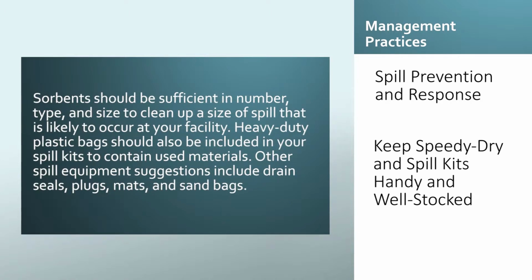Sorbent should be sufficient in number, type, and size to clean up a size of spill that is likely to occur at your facility. Heavy-duty plastic bags should also be included in your spill kit to contain used materials. Other spill equipment suggestions include drain seals, plugs, mats, and sandbags.